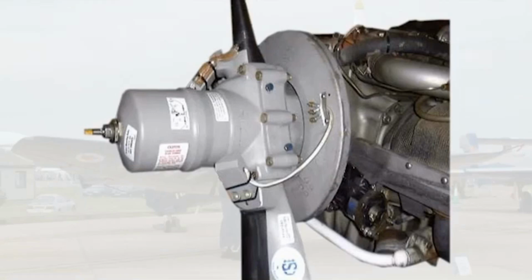Modern aircraft have propellers which are controlled automatically to vary their pitch, the blade angle, so as to maintain a selected RPM. A constant-speed variable pitch propeller permits high efficiency to be obtained over a wider range of true airspeeds, giving improved takeoff and climb performance and cruising fuel consumption.